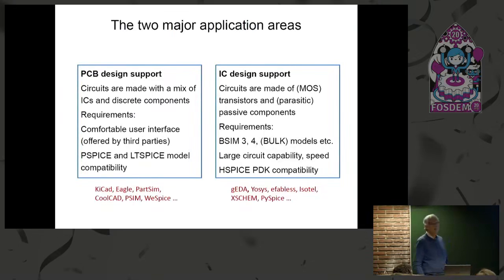Ngspice has two major application areas. The one is PCB design support. Typically here circuits are made of a mix of ICs and discrete components. There you have the requirement of a comfortable user interface. You have seen ngspice is a command line, so this is not that comfortable. So we rely on others. We rely on KiCad and some other parties to offer, for example, schematic capture. And when we do these circuit simulations, we have to be compatible with some well-known software tools like PSpice and LTSpice. This mostly concerns the device models we are using.